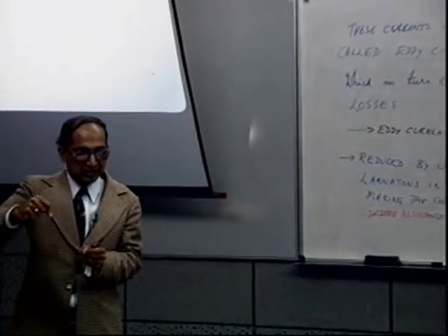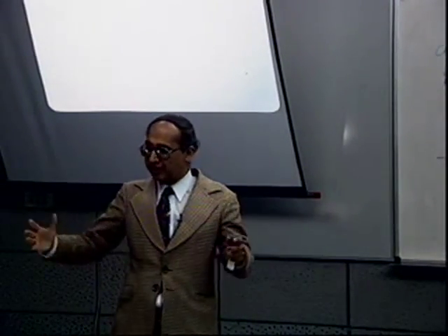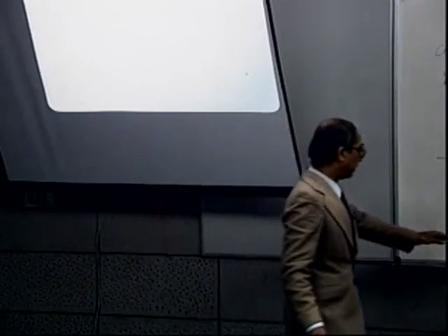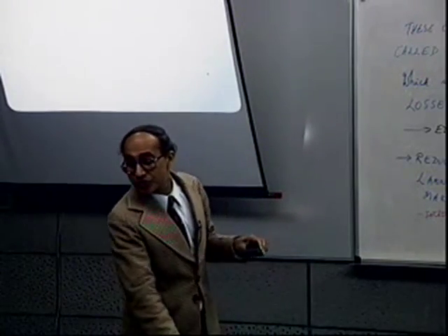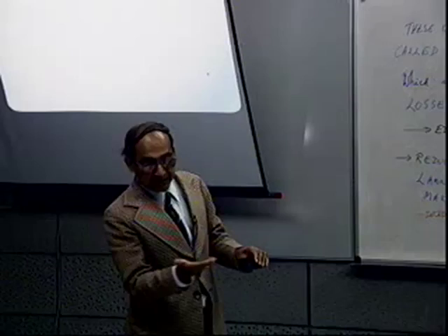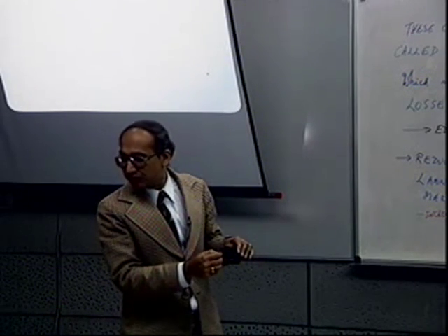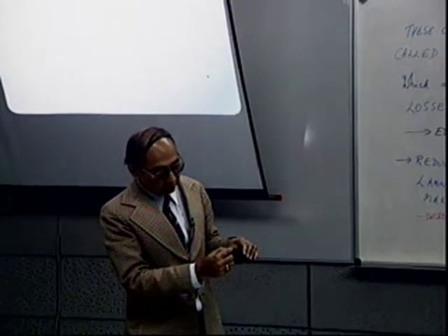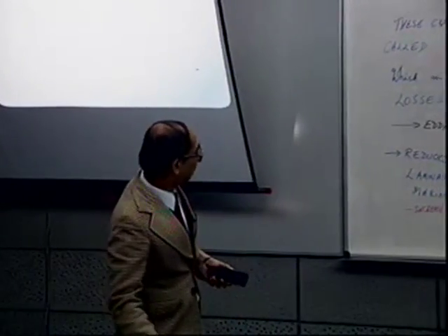In fact, very, very thin sheets. So you will observe that the currents are almost negligible, considerably reduced, instead of having all of them together like a thick conductor. If this is the eddy current which will be flowing, if there is a voltage induced, you are just cutting it into different sheets, so you will see there are very, very small currents which will go through. You are cutting it electrically. So you are almost insulating it for electrical purposes.